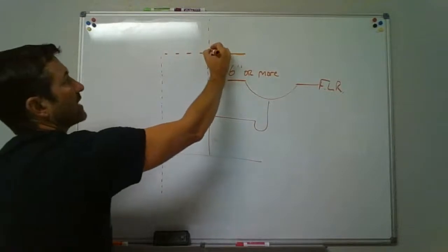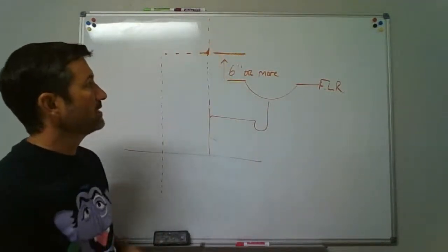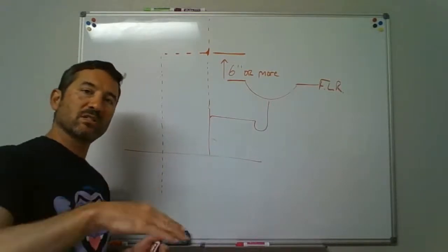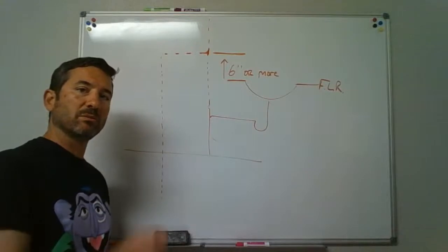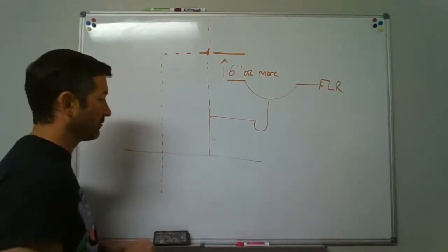Okay, well, just tie it up with a little sanitary T fitting right there would be fine. So you can make that connection, but just 6 inches. So when you're talking about laying vents down horizontal, I've got 6 inches above flood level rim. I'm going to connect one vent back over to the other 6 inches above that flood level rim on those.